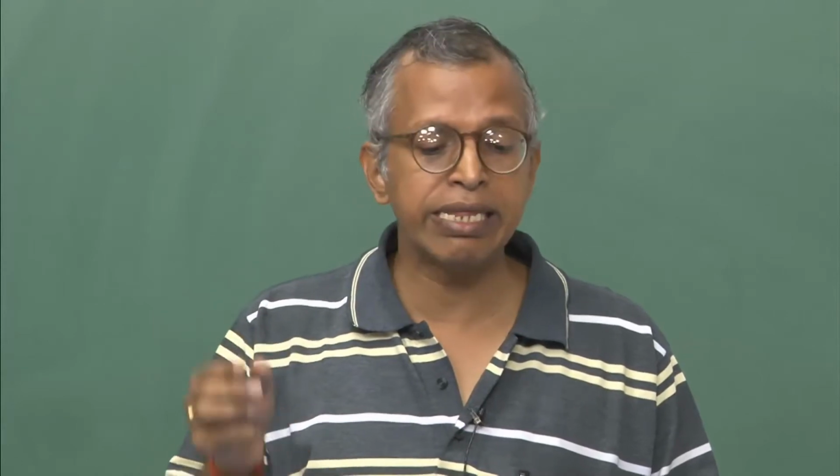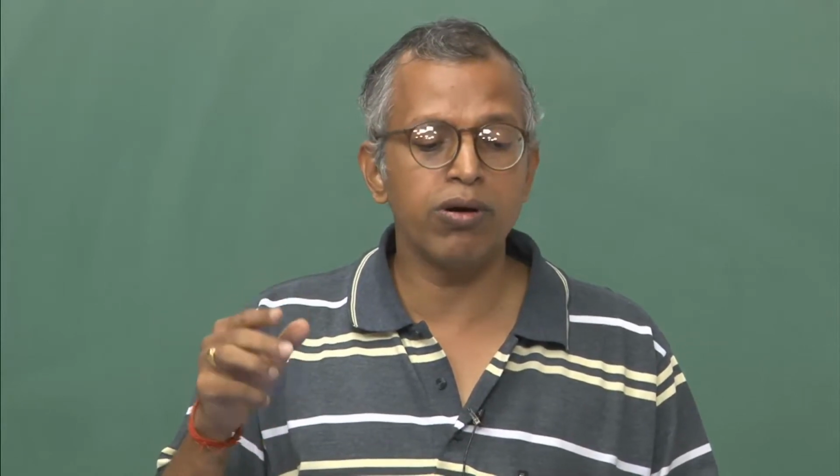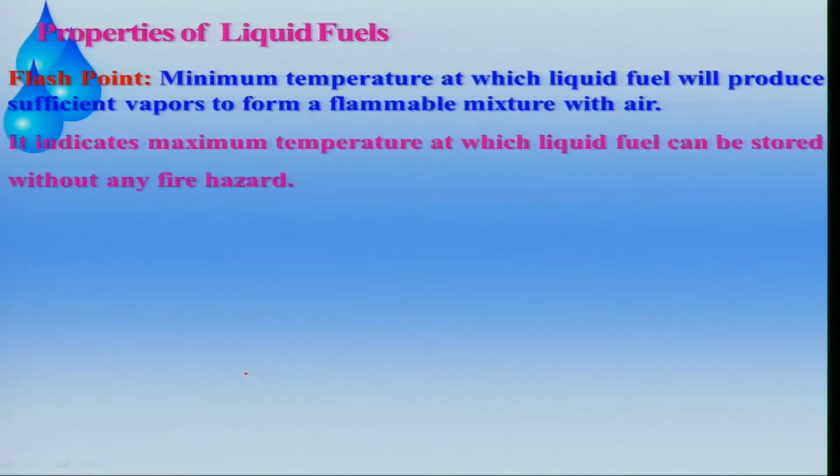In other words, this is the maximum temperature below which a liquid fuel can be stored without any fire hazard, right. So, this is a very important aspect to qualify, to say that look, I will have to store this liquid fuel under set conditions, otherwise it can incur a fire which is hazardous in nature.